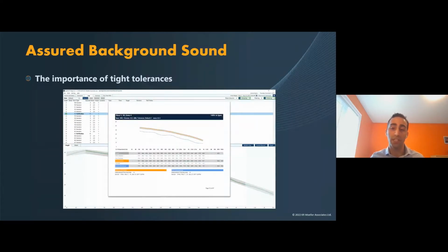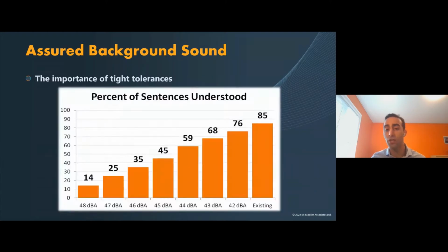However, it is within our ability to design a system that allows for localized control and to tune it to calibrate the loudspeaker's output at a position. To determine what those tolerances should be, we could look at speech privacy and intelligibility theory. Here is one assessment using the Articulation Index for a specific environment.